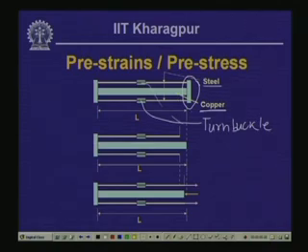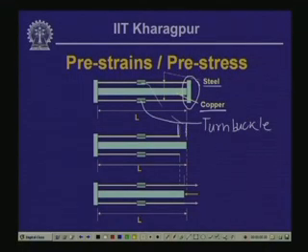Now, if we remove that, and let us say we introduce n number of turns in the turnbuckles, both the turnbuckles are turned n times, so that there is a shortening of the bar, that means the threads move inside. Since the pitch is defined as p, because of the turning of one revolution of the turnbuckle, both the threads are moving by twice p. So, n number of turns are there, and the total deformation is equal to 2np. Let us call this deformation which we introduce delta 1, which is equal to twice np.